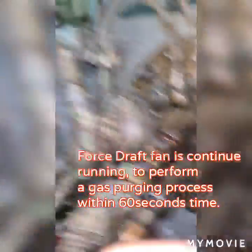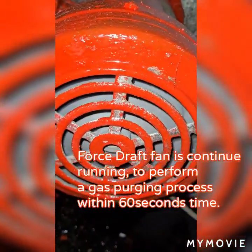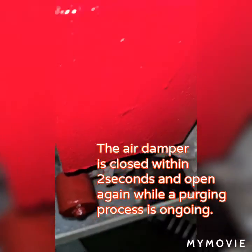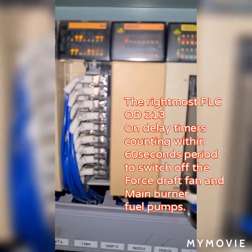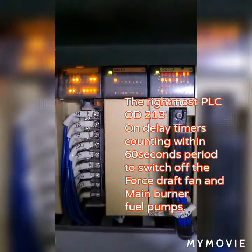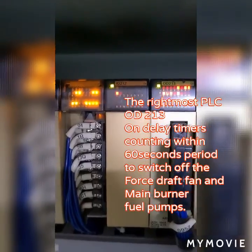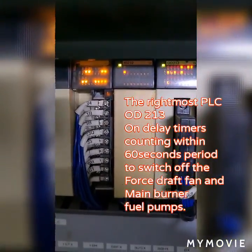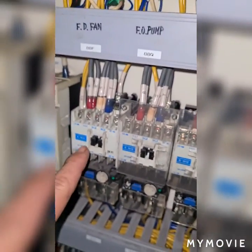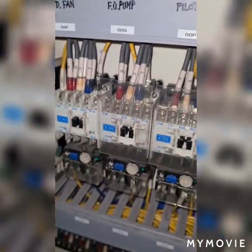As you will see here, there is no flame inside. The forced draft fan is still running to finish a 60-second purging period, and the air damper is still open. The rightmost PLC on-delay timer 213 counts within the 60-second period to switch off the forced draft fan and the main burner fuel pump. Now you can see the forced draft fan is out, de-energized. The fuel oil pump is de-energized.